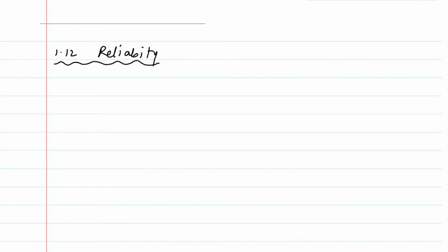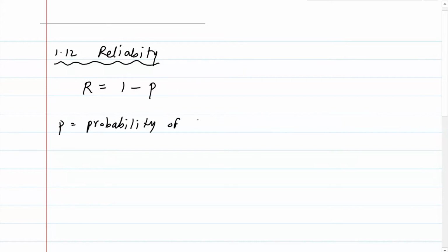And so in design, reliability is always defined in terms of 1 minus P, where P is the probability of failure. You have two choices: you can either write the probability of success or failure. Failure is more what is used. Once you know something has failed and you quantify the probability, you just compute the reliability as it not failing.